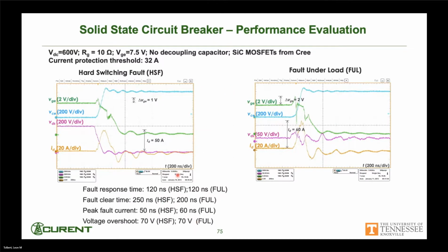Again, this had a fairly fast response time to any kind of short circuit. It was able to respond in about 120 nanoseconds for hard switch fault or fault under load, and completely cleared the fault within 200, 250 nanoseconds.